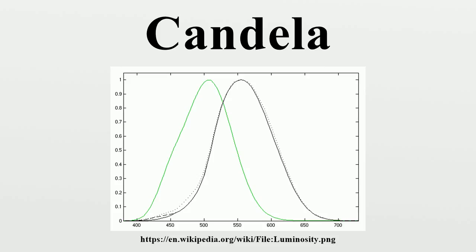The luminous intensity of light-emitting diodes is measured in millicandelas, or thousandths of a candela. Indicator LEDs are typically in the 50 millicandela range. Ultra-bright LEDs can reach 15,000 millicandelas, or higher.